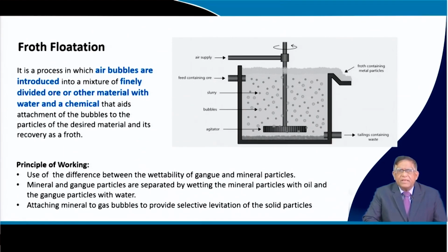For example, if certain particles, the sulfides particularly, meet oil, it has more affinity to them and they get wetted by oil, but some do not get wetted by oil, they get wetted by water. This difference of property is used in separating them out.